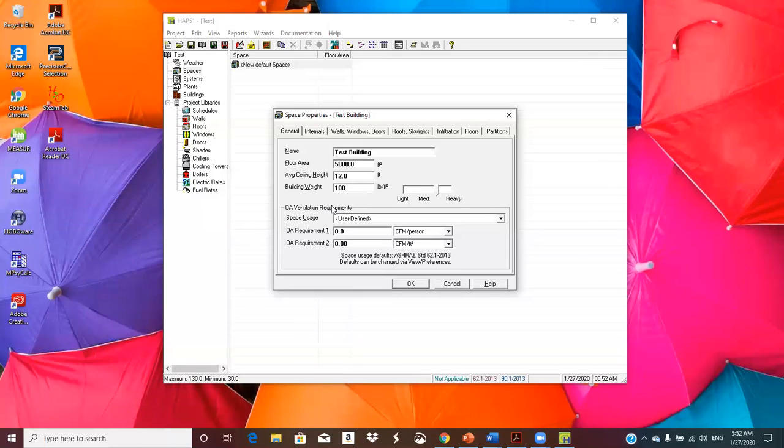Okay, so then this is ventilation. This is where we put in our ventilation air, so we can pick a particular public retail. What's a good one? Retail sales. We'll just make this a retail building. And then it goes to the ventilation code and pulls out some values. It's going to put 7.5 CFM per person plus 0.12 CFM per square foot of area. And that's how it's going to determine the ventilation air that goes into this.